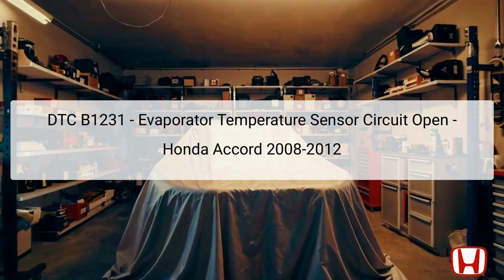The DTC B1231 in the Honda Accord models from 2008 to 2012 indicates an open circuit in the evaporator temperature sensor. The evaporator temperature sensor plays a crucial role in the vehicle's climate control system by monitoring the temperature of the evaporator to ensure proper cabin cooling.